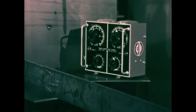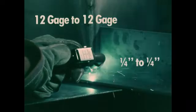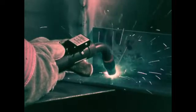As the vertical down weld of the 12 gauge metal is completed, the operator simply depresses the trigger all the way down, and the system automatically provides the proper amperage and voltage value needed to weld the thicker metal. This dual schedule convenience is a recent addition to modern electric arc welding and is being installed in more and more educational and industry locations.